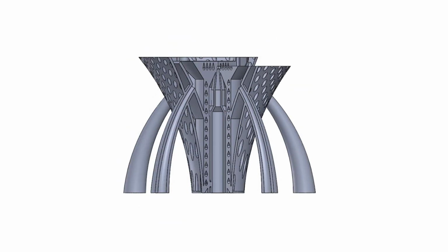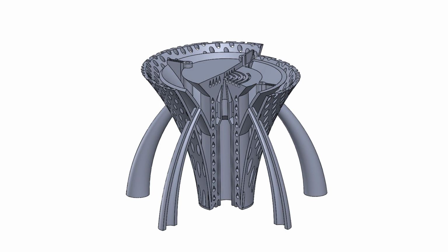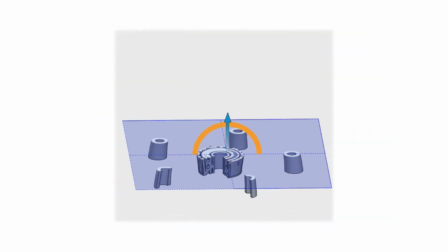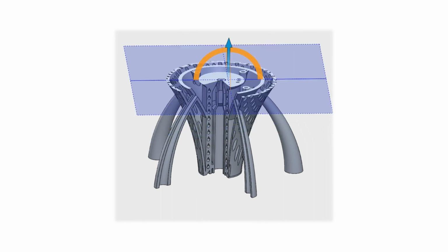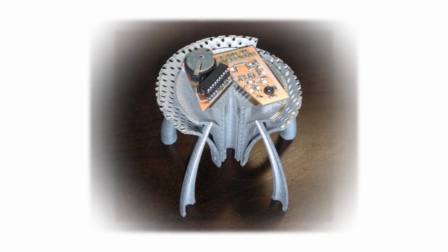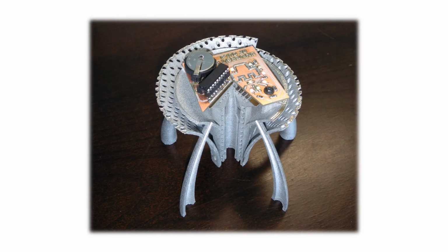The material is aluminium Al-C10Mg. The height of the part is 90 mm and the weight is 265 grams. The part consists of 5 hollow legs. The outermost has a perforated protective shell. The holes are made so that they are vertical. Inside the protective shell there is a frame structure consisting of a funnel-shaped outer part, and an inner structure contained in a helical cooling duct system. The cooling channels are teardrop-shaped. And here is the finished structure with the electronics.